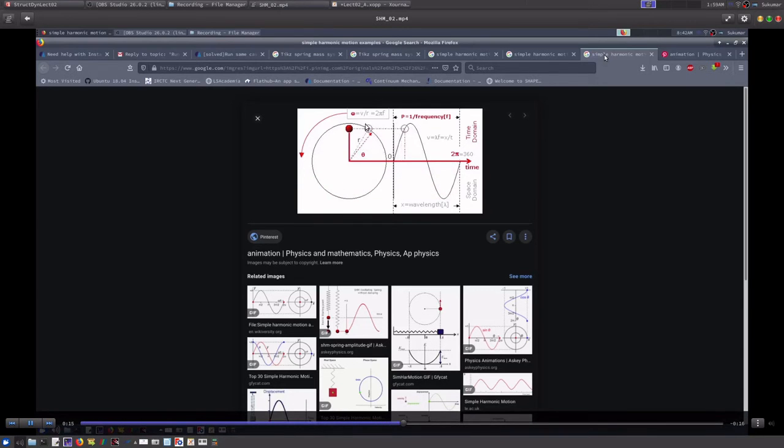You see here an undamped free vibration is shown where the displacement of this mass is shown as the vertical motion of this bob, and this is related to the circular motion of another body with a radius r. Usually we take this r as unity, and we see that the motion is repeated after a full rotation along the circle, which has a period of twice pi.